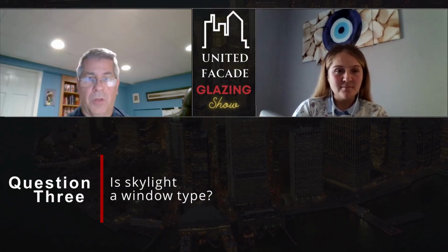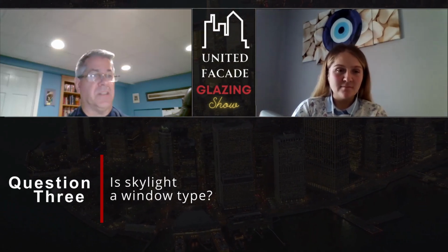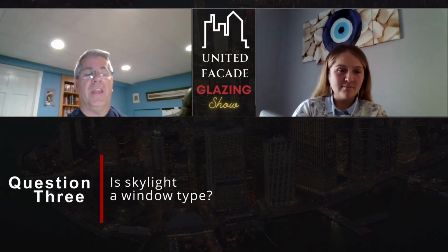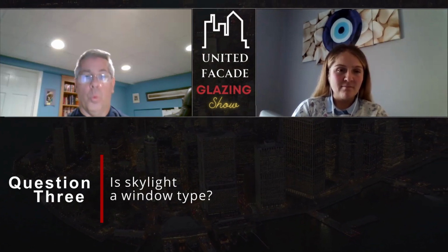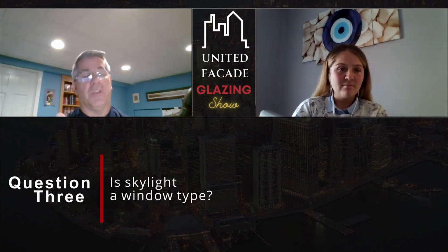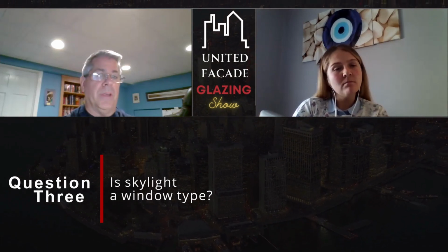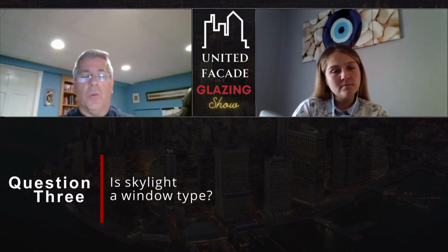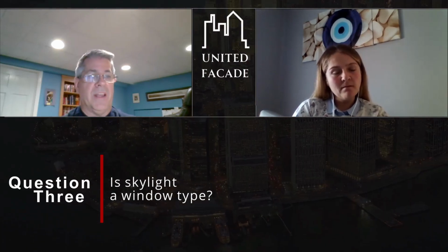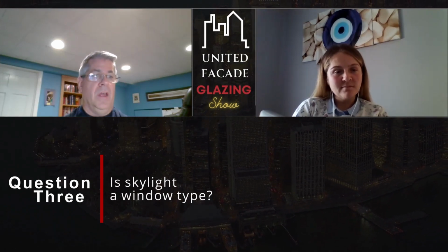It's going to be double sealed to make sure we don't have any water penetration coming in, because that's the last thing you're going to want if you have it in your house with a wood framed roof with shingles on top of it. You get water onto the wood, you don't want the wood to rot. Yeah, you're right. Building is a little bit different, but still, nobody ever wants water penetrating into the exposed or living areas.